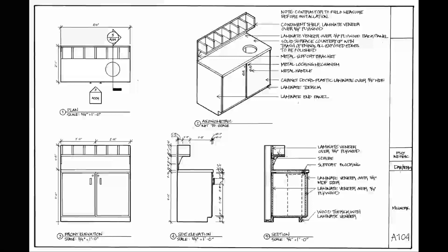So you can see here I'm giving just a little bit more information about the dimension size and the breakdown because more detailed information is coming across in that side elevation. But what you can see here is just very simple indications. Again, major profile line in my thickest line weight, change of plane lines where I could get away with it, and it's a little bit more forgiving here because there's less angle, so I was able to use my 0.3 most of the time.